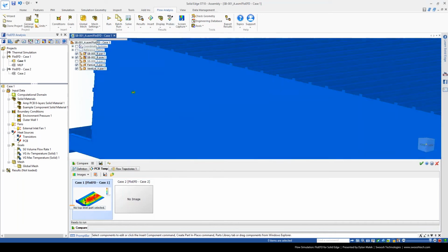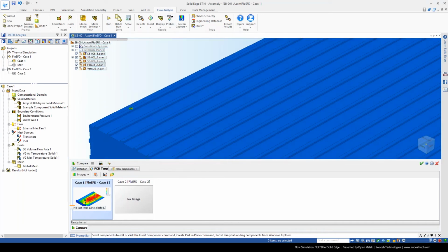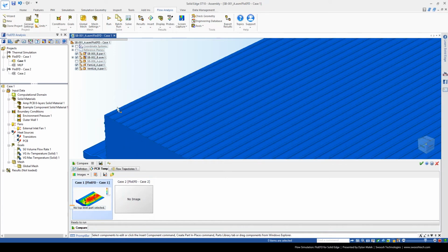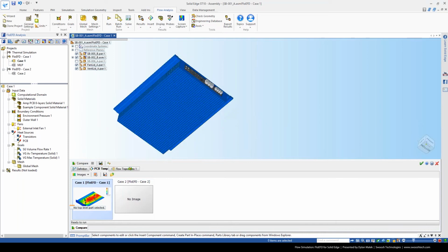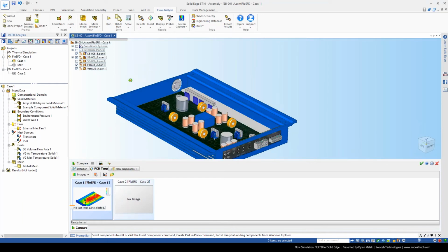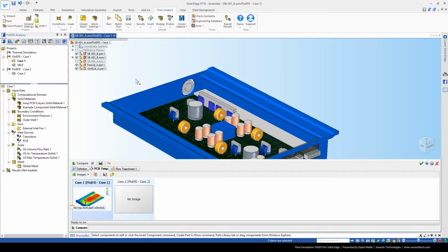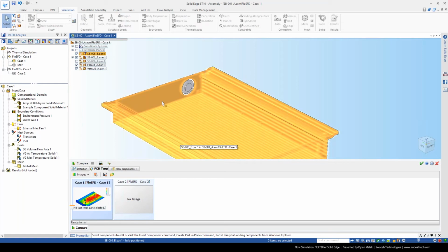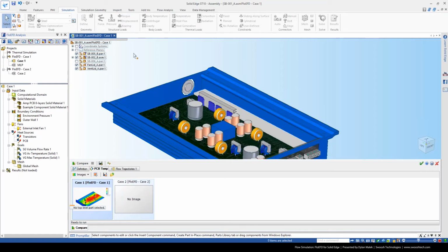And again, when you're thinking about finite element analysis simulations, you always want to simplify the models. You don't need to have the radiuses and a lot of complex features to actually get an accurate study. It's just going to increase the speed of the study. So if you have a really great computer, have at it, keep the geometry as is. I'm working off a laptop and not as much power, so keeping it simple is where I need to keep it.